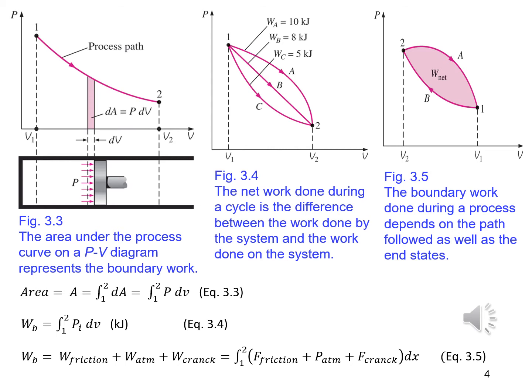If the relationship between P and V during an expansion or a compression process is given in terms of experimental data instead of in a functional form, obviously we cannot perform the integration analytically. We can, however, plot a PV diagram of the process using these data points and calculate the area underneath graphically to determine the work done.